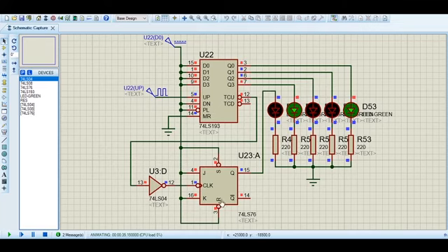So that means this flip-flop will just continuously toggle between 0 and 1 whenever its clock here is triggered by the carry out output or the terminal count up output of the 74LS193. A NOT gate is added here to delay the triggering of the JK flip-flop, since the JK flip-flop is a negative edge triggered flip-flop.